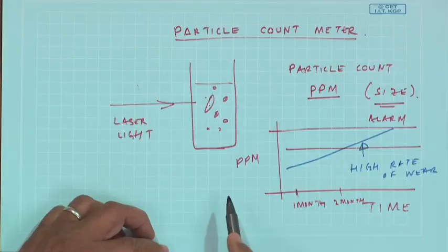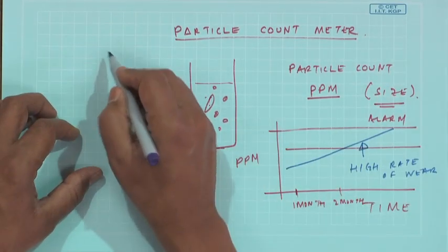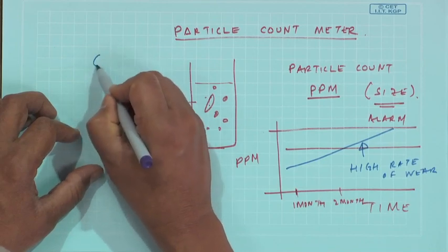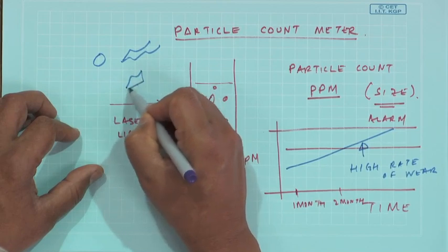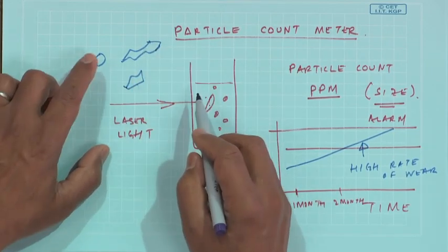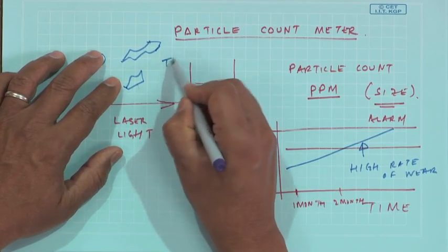Is it suddenly wearing very fast, or are there any foreign components, for example, dirt that has got into the system. And of course, with the wear particles, some particles we will see later on, some are circular, some are like plates, some have sharp edges. So, this also gives us the morphology, an idea as to the type of wear.